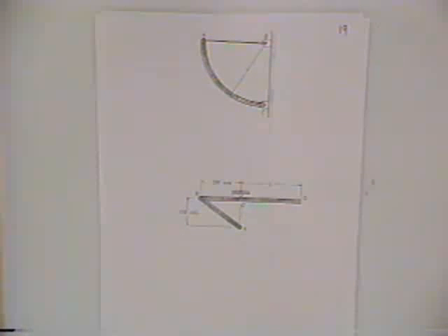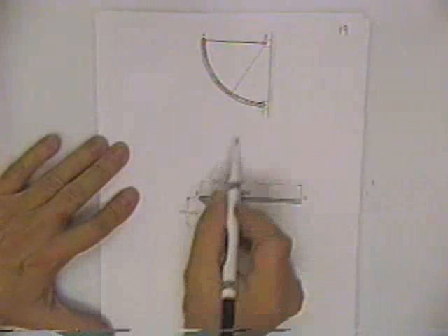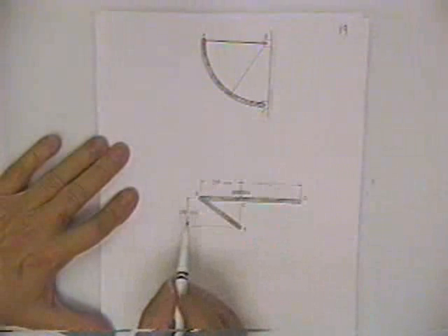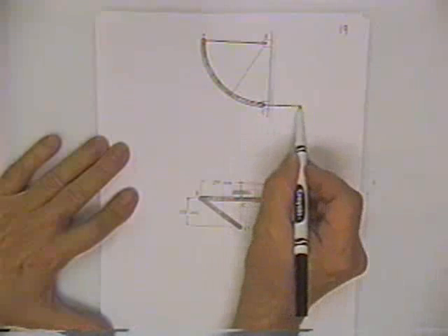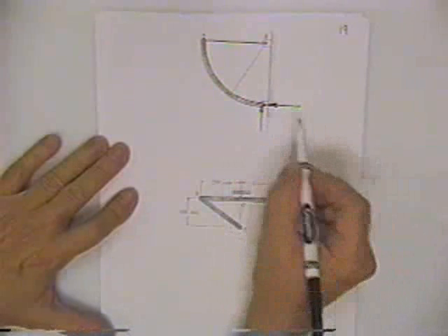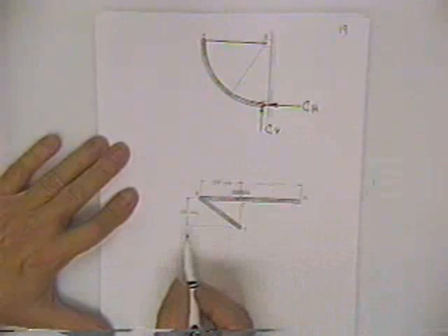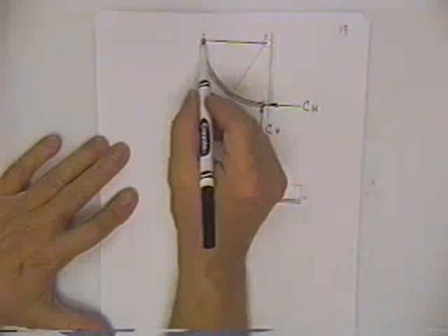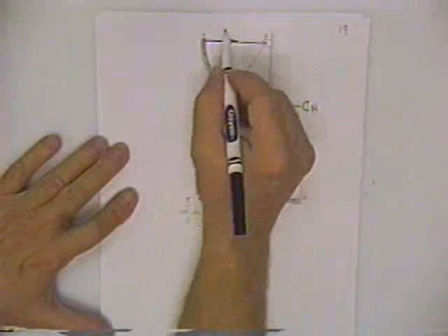Now then, let's say you have a bar, and that bar is supported by a pin at C and is supported at A by a rope. We'll discuss more about pins and rollers and stuff like that later, but I think most of you probably remember that pins have the ability to produce two forces. That would be C horizontal and C vertical. Those are both unknown.